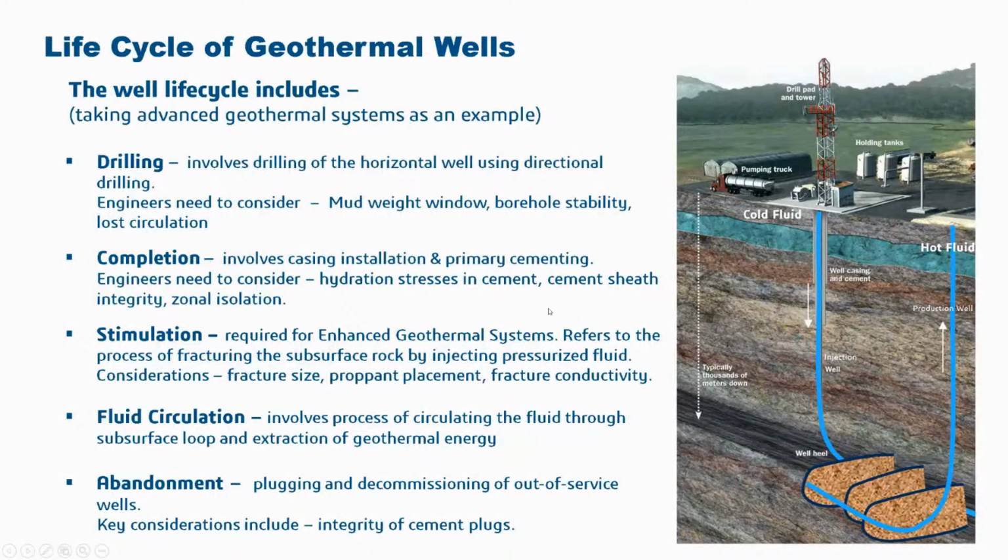So let's go through the life cycle of a geothermal well. The life cycle of a geothermal well includes drilling. Drilling involves drilling of the vertical and horizontal section of the well. And during the drilling, engineers need to consider concepts like mud weight window, borehole stability, and loss circulation, the typical concepts that you use in drilling of oil and gas wells.